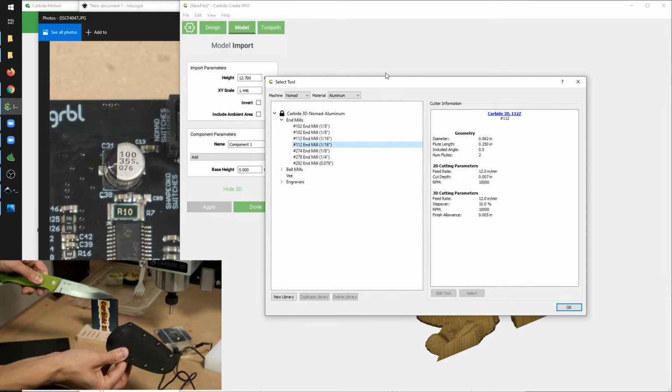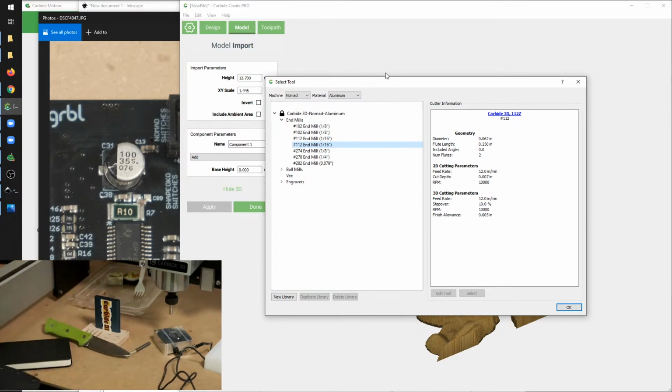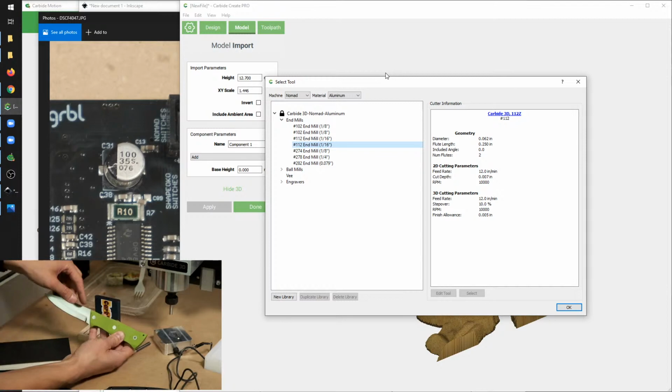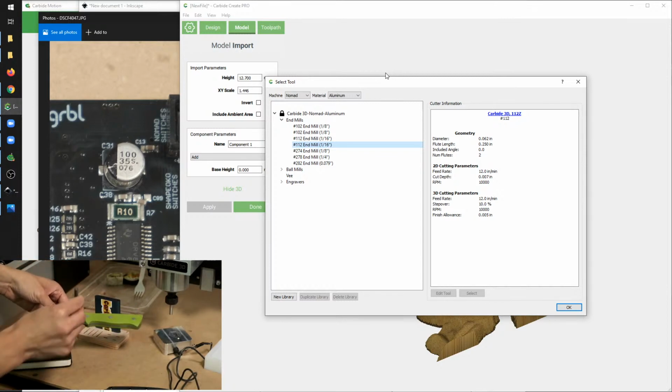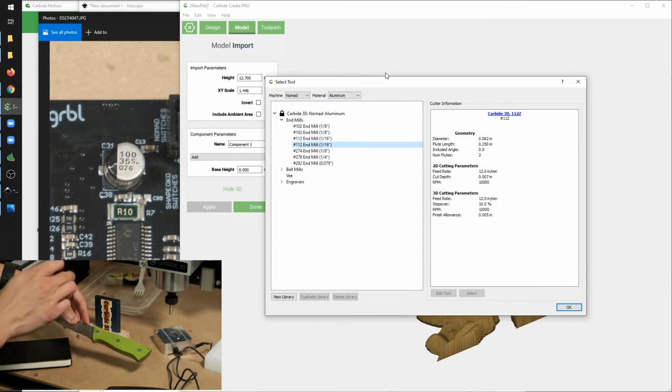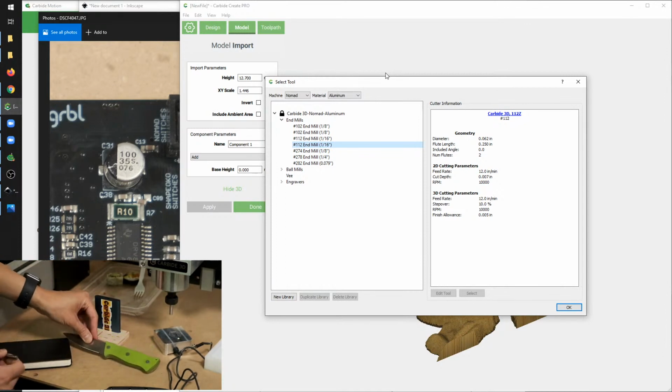That being said, we do have a project, the Carbide Camp Knife, where I machined the bevels for this blade in Carbide on the Nomad. This was using Fusion with adaptive cuts on here. I don't think you could see, you can see some chatter marks in there. That's because I had inefficient tool pathing, as the cutter was basically coming in to a sharp corner and making a sharp 90-degree left turn. That's what caused that chatter there. But this is just a proof of concept, slow and tedious, but tool steel machining on the Nomad.